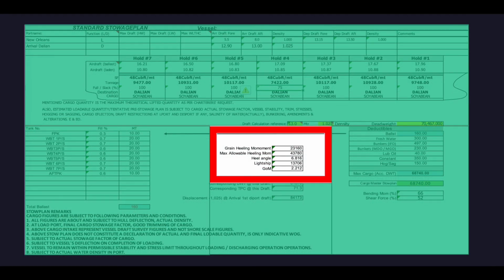The grain mainly has two hazards, namely settling and shifting. Both these factors affect the stability of the vessel. Two crucial things are required to be considered for carriage of grain. 1. The ship should have a valid document of authorization. And 2. The ship should have an approved grain stability booklet, grain loading manual.